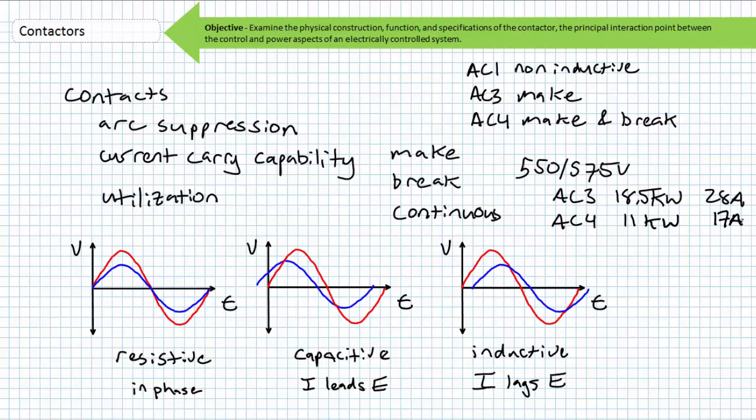However, this same contactor can only handle 11 kilowatts and 17 amps when used for AC4 purposes. In contrast, NEMA contactors are given size ratings based on current, voltage, and power, since an operator may not know the planned application or the duty cycle of a load. NEMA contactors are built with sufficient reserve capacity such that each contactor spans a larger usable range. This really highlights the distinction between NEMA and IEC philosophies, that of robustness, interchangeability, and generality versus specificity, purpose, and limited scope.